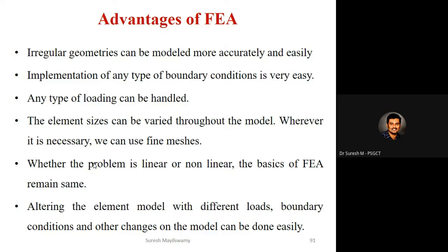Whether the problem is linear or non-linear, the basics of FEA remain the same. You can solve it in a linear way or a non-linear way, but the procedure is the same. You discretize, make nodes and elements, then apply the boundary conditions, and then solve the problem. Altering the element model with different loads, boundary conditions, and other changes can be done easily.